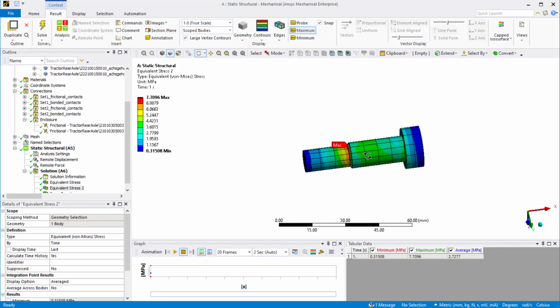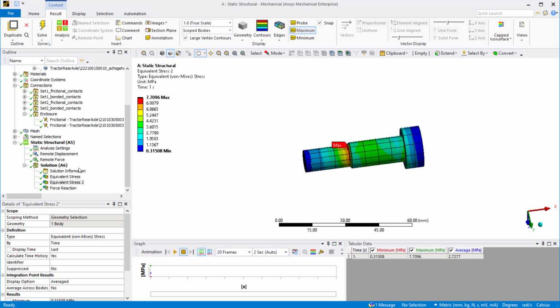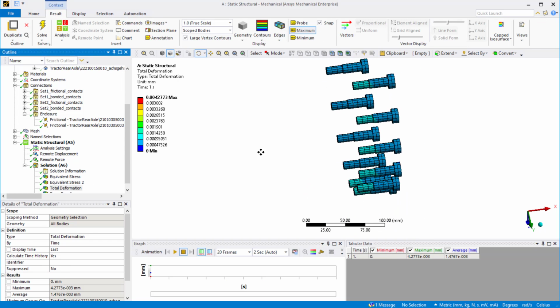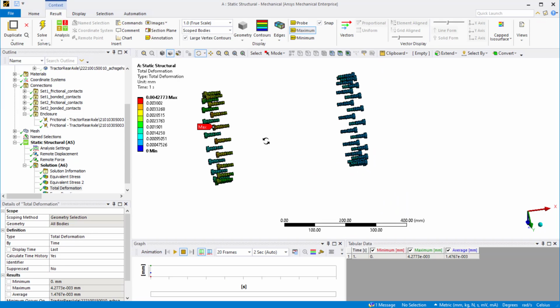This way, we can use the bolted connections in assembly to study the reaction forces, and we can also check whether the selected bolt fasteners can support the load without undergoing plastic deformation. With this, we can conclude this workshop.